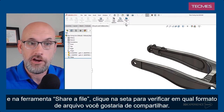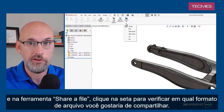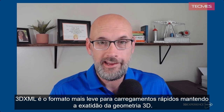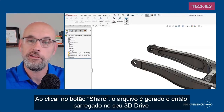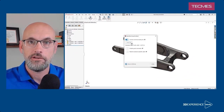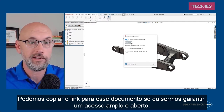Now under Share a File, first click on the arrow to verify which file format you'd like to share. 3D XML is the lightweight format for short load times while maintaining exact 3D geometry. Once you click the Share button, the file is generated and uploaded to your 3D drive in a folder named Share with External. Now we can copy the link to that document if we want to grant wide open access.